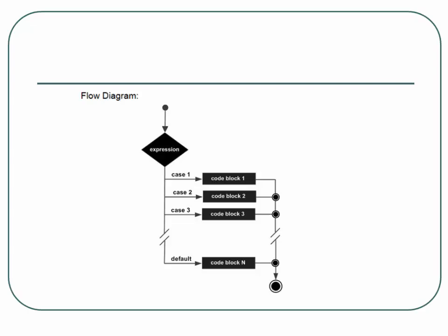So for example, for our wash machine, and I'll do this on a side note, I don't have that there until I finish the slides. But we have something that looks like this. Here's a very simple one, and we'll use this as an example to start our wash machine. This is the way we would normally do our finite state machines in C. We set up an enumerated type called my state. In this particular case, we say states 1, 2, and 3. We would list all of our states in that list.